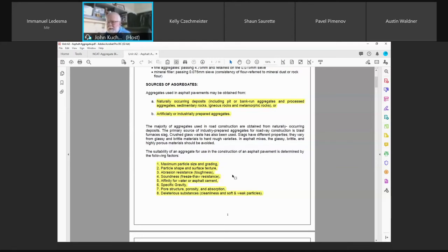And you guys did crush counts last year with Natalie. Well, there's a specification if you look at City of Winnipeg, and most agencies have a crush count. They have a crush count specification, 2 fractured faces. Then they know they've got the crush. Abrasion resistance or the toughness. Many times you can look at a tough aggregate, okay? But sometimes the Los Angeles abrasion or the durability is off. And we'll look at a chart here right away.